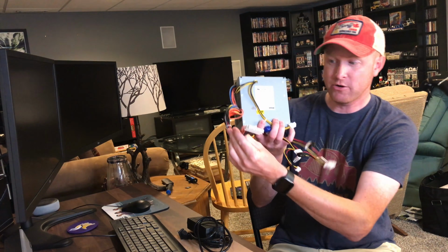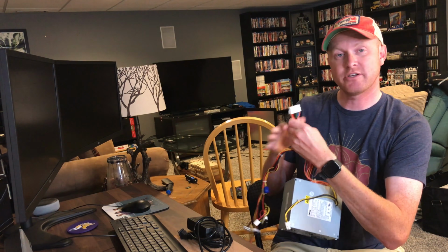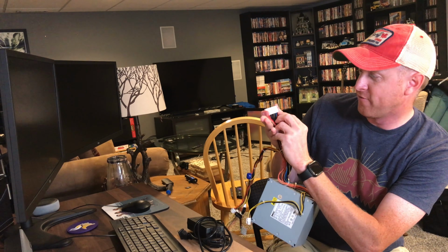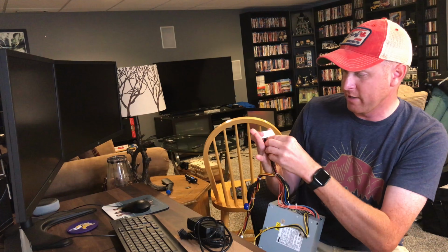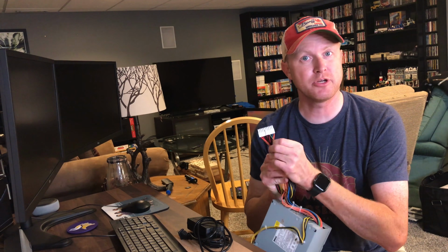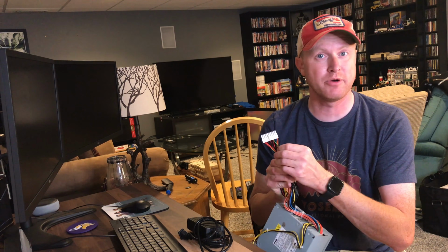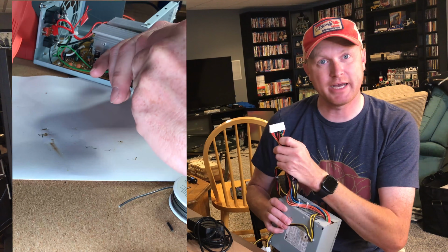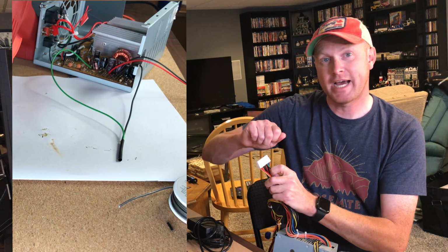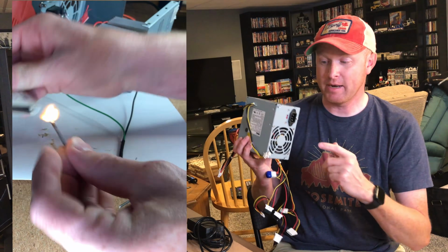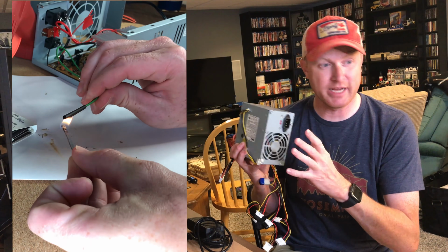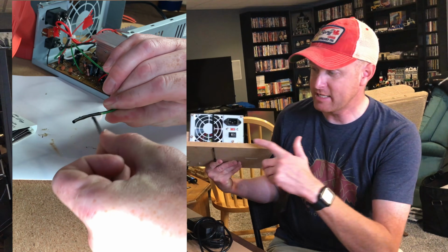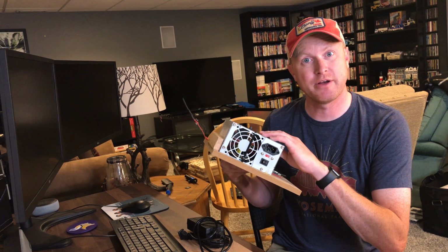If we were to look at our power supply and grab the really fat connector that connects onto the motherboard, if we were to look at these wires, the 4th wire over is a green wire. This green wire connects to the computer motherboard and detects when you push the power button on the computer. So what I did was take these 2 wires, the green and the black, I stripped them out, tied them together, and now whenever I add power to this power supply, it'll turn on. Or in the case of mine, anytime I turn the on-off switch, it'll power on the power supply.